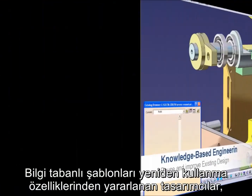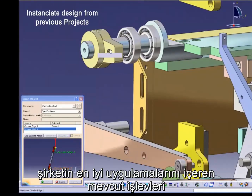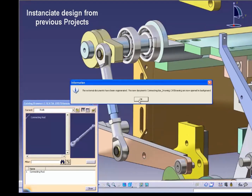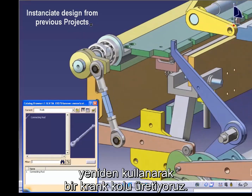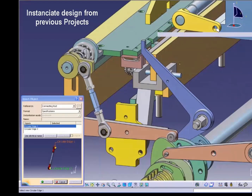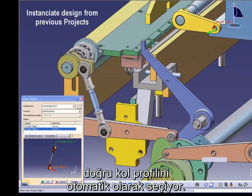Using knowledge-based templates reuse capabilities, designers boost their productivity, reusing existing functions or components that include companies' best practices. For example, here we generate a connecting rod reusing a smart template stored in a catalog. An embedded design rule automatically chooses the right rod profile depending on the rod length.